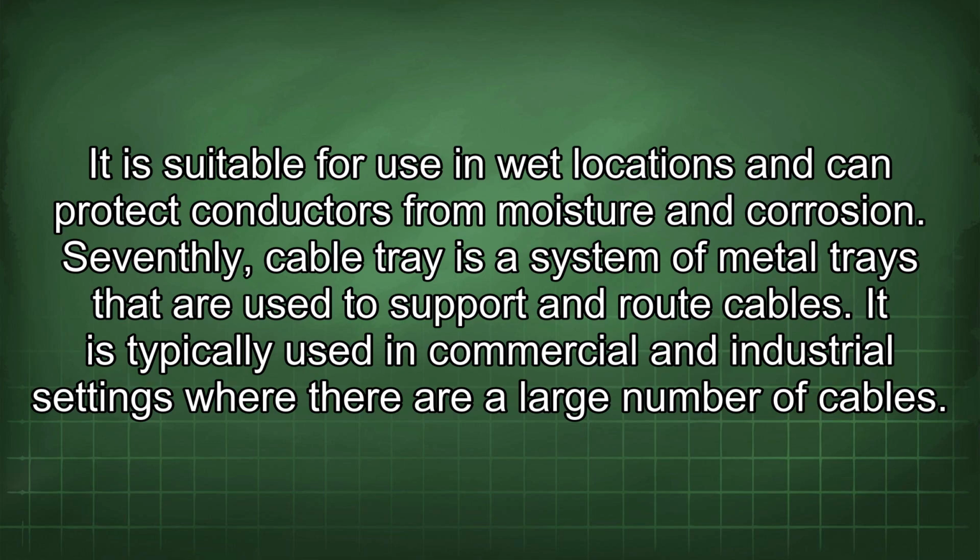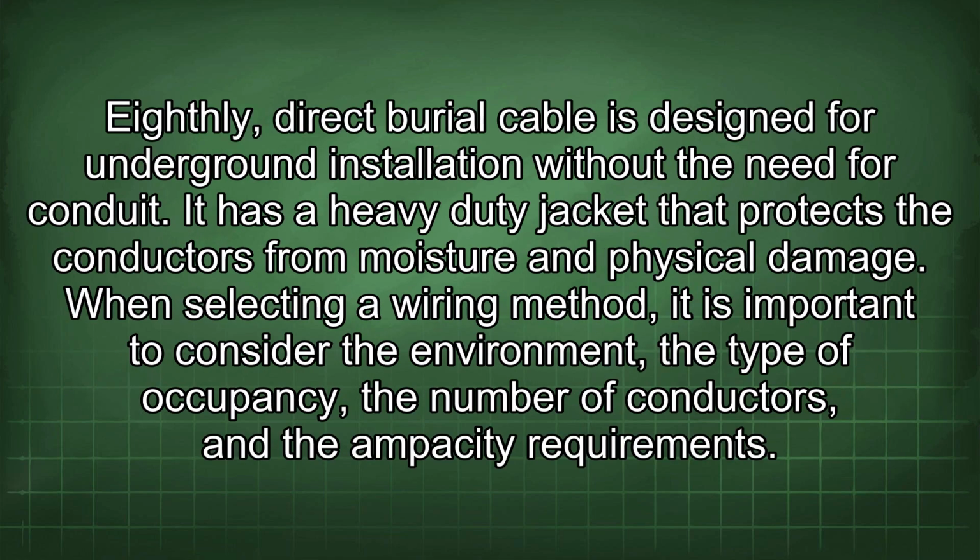Seventhly, cable tray is a system of metal trays that are used to support and route cables. It is typically used in commercial and industrial settings where there are a large number of cables. Eighthly, direct burial cable is designed for underground installation without the need for conduit. It has a heavy-duty jacket that protects the conductors from moisture and physical damage.